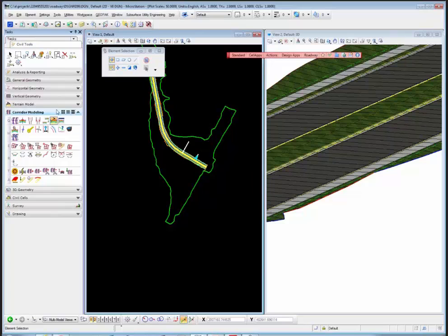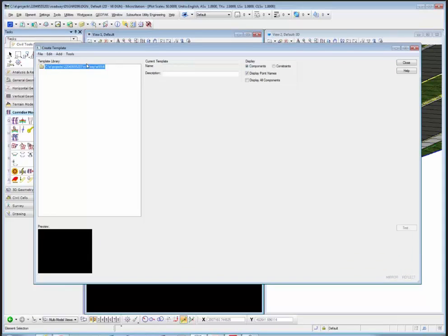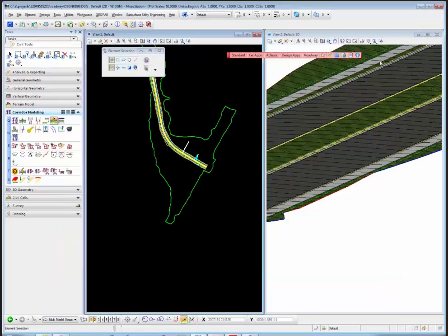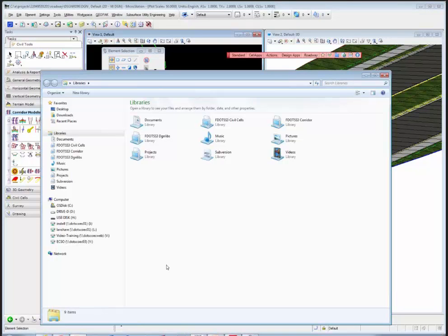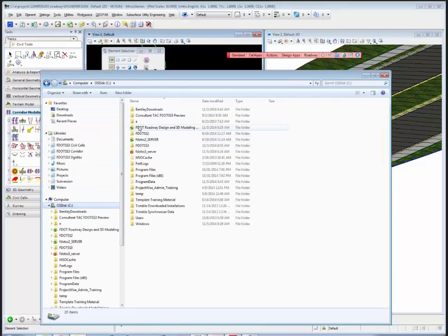It automatically loads the f.ss3, and you'd always have to go back and do a file open in order to get your project ITL file. So we kind of put our heads together, and what we decided was if you keep in your project folder an ITL file with the same name as the project, then we can launch that ITL file instead of the f.ss3.itl file. What does that mean?